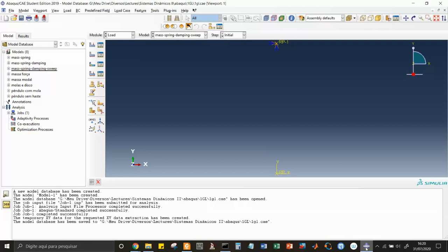This force has a frequency and is applied in a harmonic fashion. Then we are going to go for the next frequency, get the response, go to the next, and so on until we get a full spectrum of frequency in a range that we are going to define. And for each frequency, we are going to capture the response of the system, meaning the displacement of the mass.